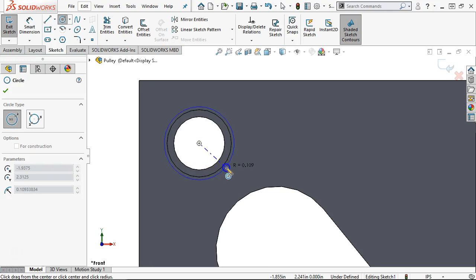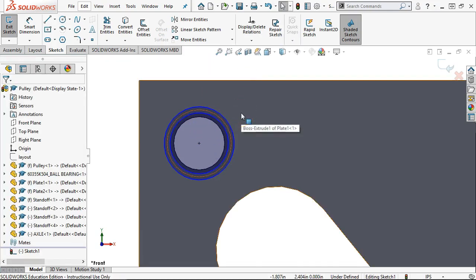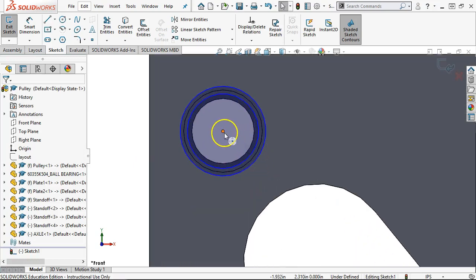True position is that we have our tolerance zone, but in effect, the location tolerance is going to be to this center point, not necessarily to the holes. Depending on our inspection method, I can take a pair of calipers and measure from this edge to the outside and get an approximate. But I know as soon as I touch off on the first part and drill those holes, take that piece out, put the second one in and drill the second set of holes, just in the process of banking that part into my stop, I have a slight variation.